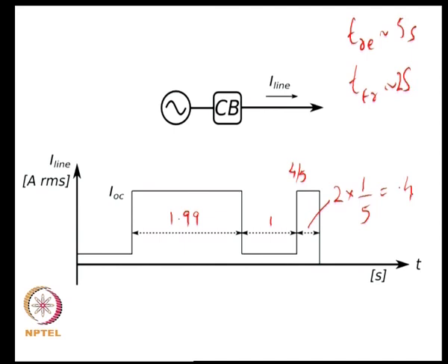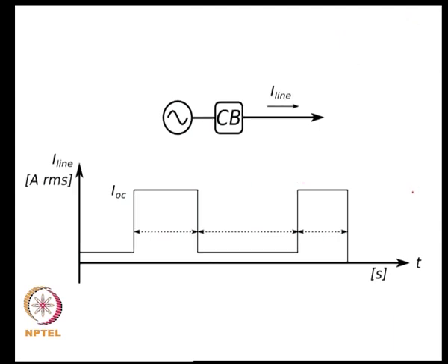So, you can see that assuming constant tripping rates and reset rates, you can actually look at what happens when currents go up and down in some switched manner. Okay. So, if you had another situation where you had a similar level of overcurrent and the overcurrent lasted for 1.99 seconds, and then the current went away or came back to a level much lower than 1 for, say, 5 seconds, it means that at this point your circuit breaker is fully reset.